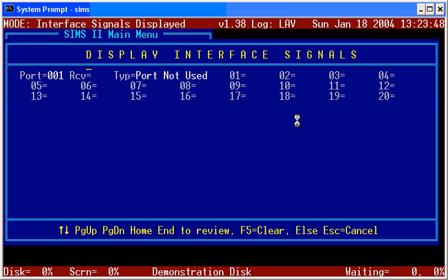In order to capture the protocol, I simply must go to the primary workstation, the one that's connected to the receivers, of course, and I can go down and select the receiver that I want. At that point in time, I can look for the signal that comes in, hit a space bar, and then I can do a print screen or write down what that protocol information is coming across. That's very, very important to assist SIMS support personnel to deal with receiver problems.